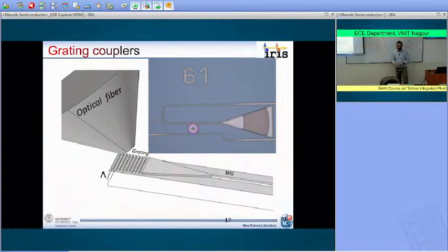And so during the optimization, during the design, I know that you are doing some design in your courses. Those are aspects that you need to take care of. You want to optimize the quantity of light that is reaching the waveguide here. And therefore you have to optimize the shaping, the curvature here, in order to focus the light there, as well as avoid any loss in this part of the grating. And therefore you have to carefully design the tapering.